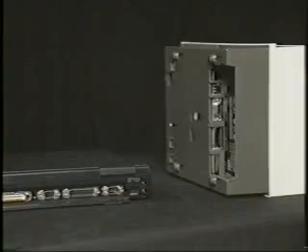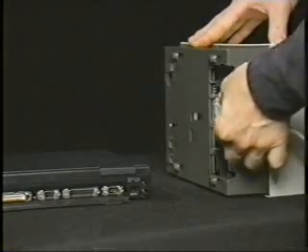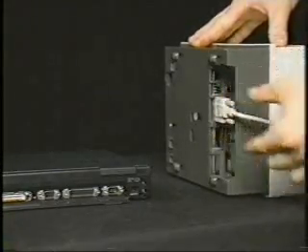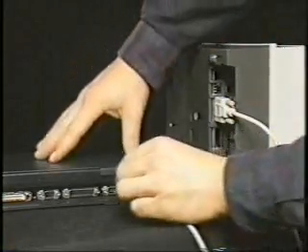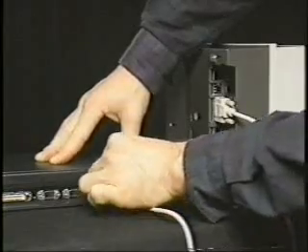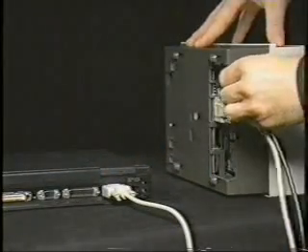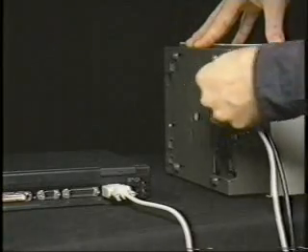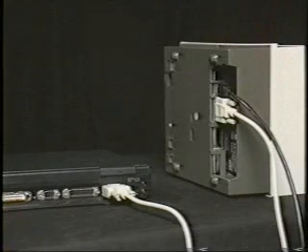The 4610 printer has several online tests. These tests are run from a laptop computer using the service diskette. Ensure that the power is off on both the printer and the PC. Connect the RS-232 cable to the PC and the printer. Connect the power cord to the printer. Then plug in the DC power adapter to its 115 volts AC source.